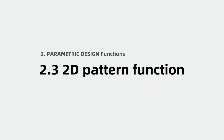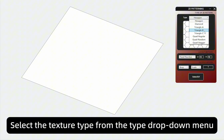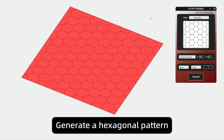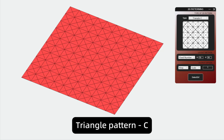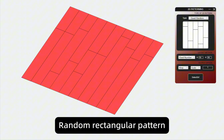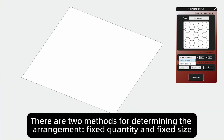2D pattern function. Click the 2D patterning button to open the pop-up window. Select the texture type from the Type drop-down menu. There are 8 different textures built into the system to choose from: hexagonal pattern, rhombus pattern, triangle pattern A, triangle pattern B, triangle pattern C, regular rectangular pattern, random rectangular pattern, brick rectangular pattern. There are 2 methods for determining the arrangement: fixed quantity and fixed size.